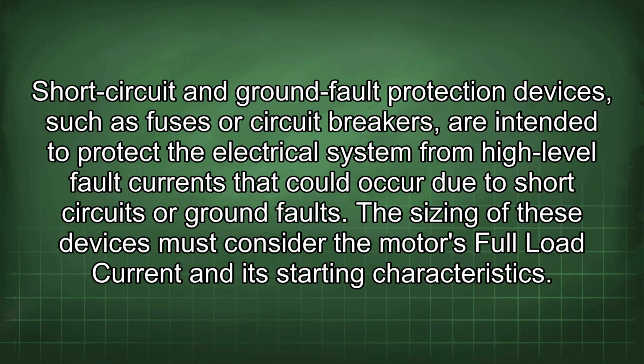Thirdly, short circuit and ground fault protection. Short circuit and ground fault protection devices, such as fuses or circuit breakers, are intended to protect the electrical system from high-level fault currents that could occur due to short circuits or ground faults. The sizing of these devices must consider the motor's full load current and its starting characteristics.